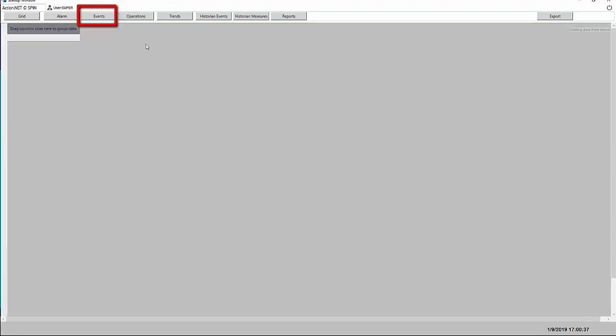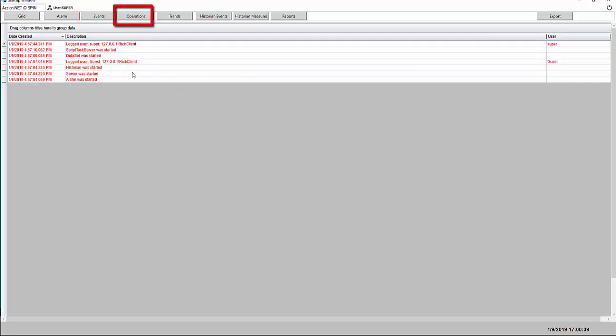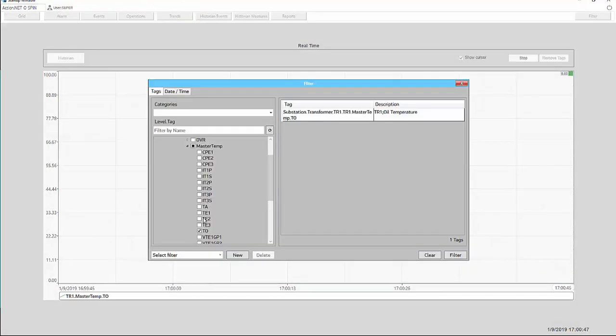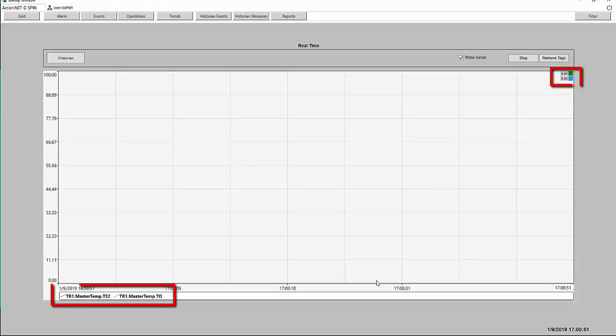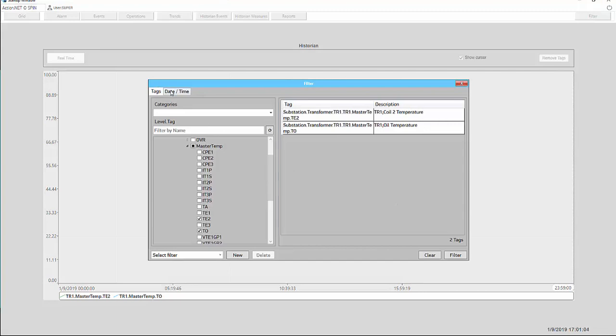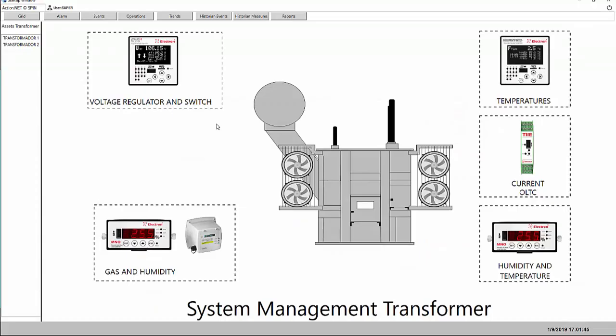In conclusion, within a few minutes we generate an application that, once integrated into the transformer monitoring IEDs, immediately starts reading the IED data and sending it to the control center. If a technician is in the substation, he can access, via tablet or laptop, dashboards with the transformer monitoring screens. If communication with the center fails, the gateway stores the data locally for more than 1 month. If we register the different IEDs of the transformers as components, we can generate a generic data collection application with several IED options in minutes, with minimal possibility of error.